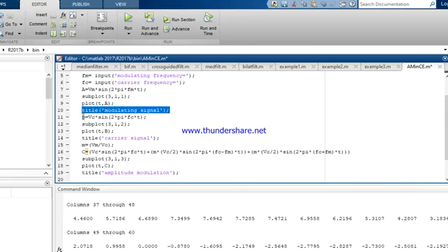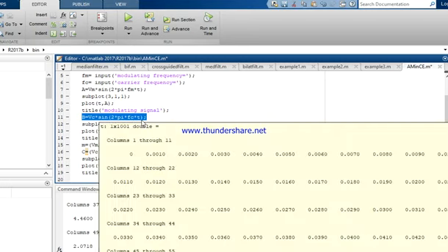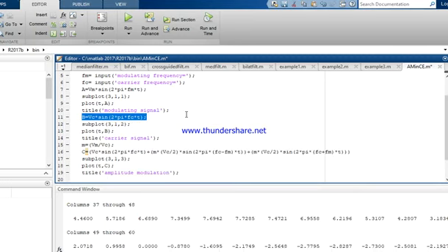Then we are going to put B equal to Vc star sine of 2 star pi star Fc star t. Again we can put the formula for this command. Then we know the value of Vc, we will put the Vc value, the Fc value, and the t value already from 0 to 1 with subdivision of 0.001. This is our carrier signal.